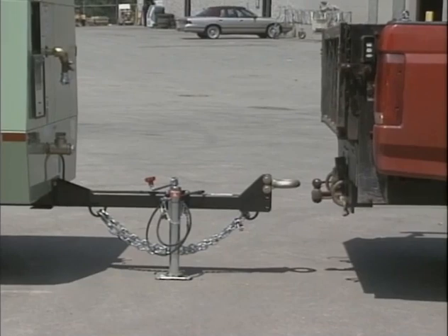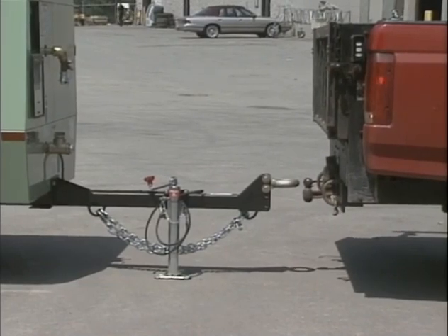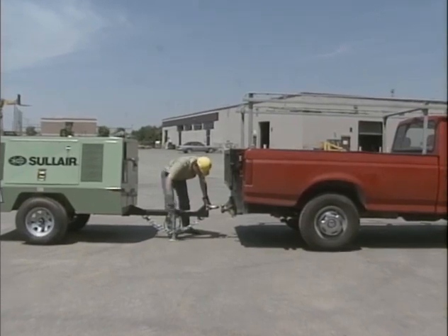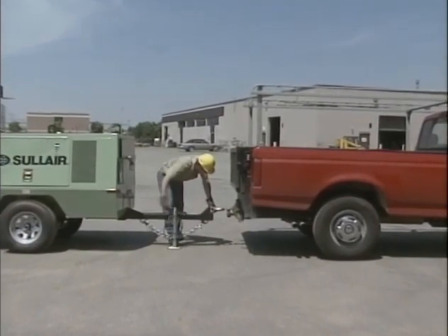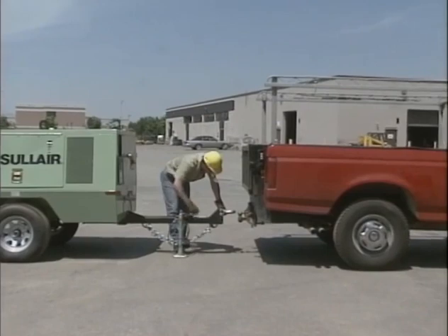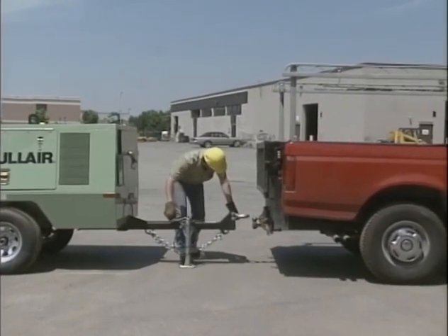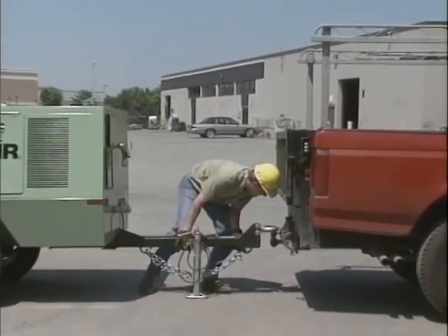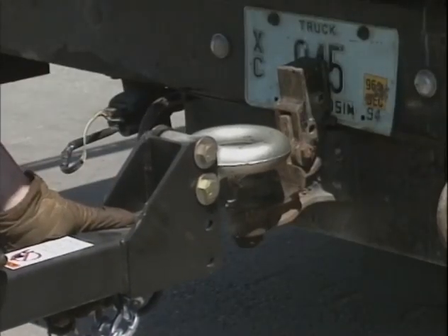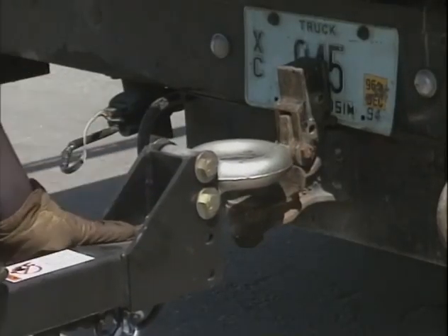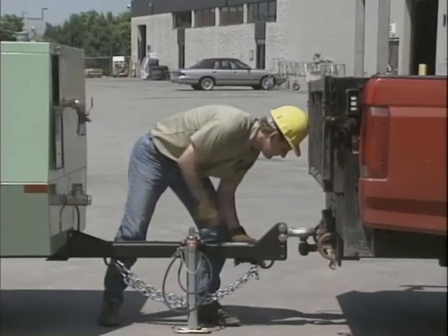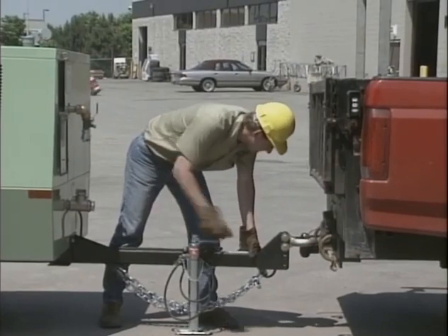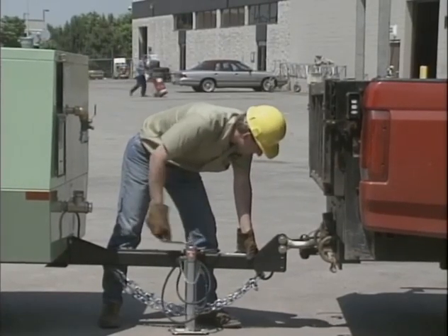If the air compressor is provided with a drawbar latched in the upright position, carefully unlatch the drawbar and lower it to engage the coupling device. If not, raise the drawbar to engage the coupling device or otherwise couple the air compressor to the towing vehicle. Do not attempt to raise or lower the drawbar by hand if the weight is more than you can safely handle. Use a lifting device, such as a jack, if you can't lift or lower without injury to yourself or others.